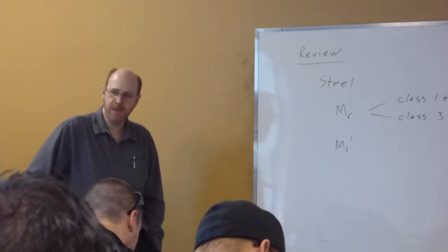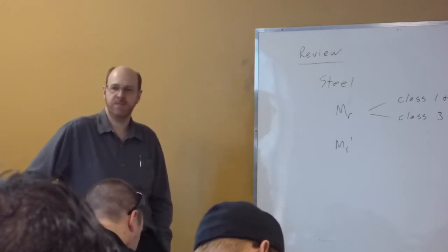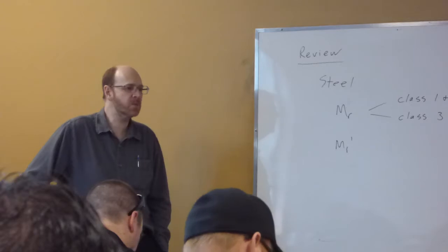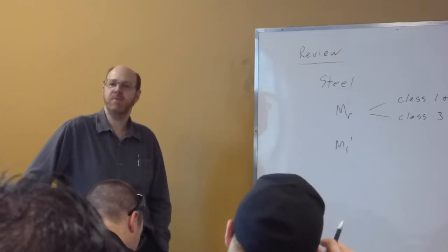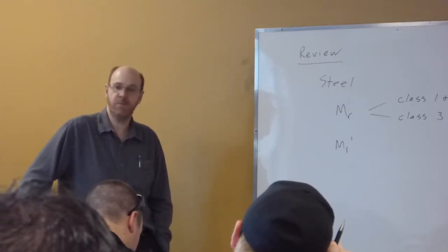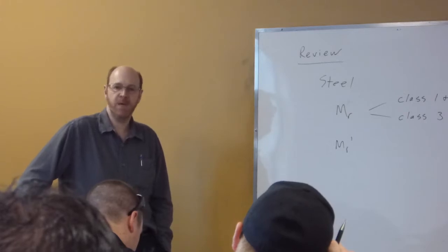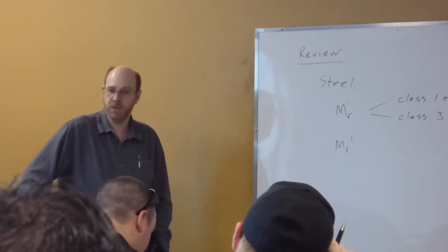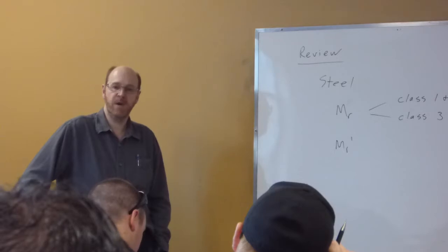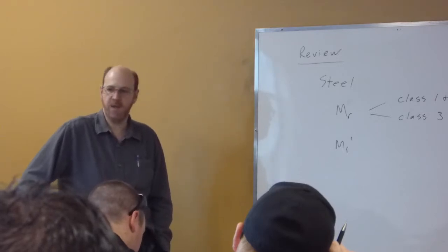The one exception to that is if I'm using HSS. With an HSS section, we can basically guarantee that we are going to get Canadian produced sections. So if I'm doing an HSS section by hand, I will actually use 350 MPa for that. But for anything else, I'll use 345 MPa.